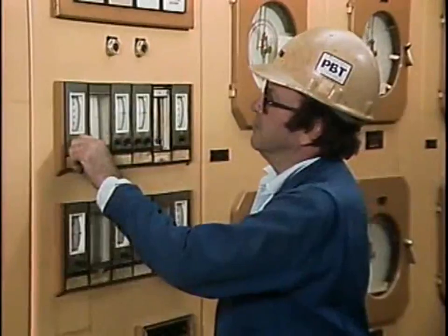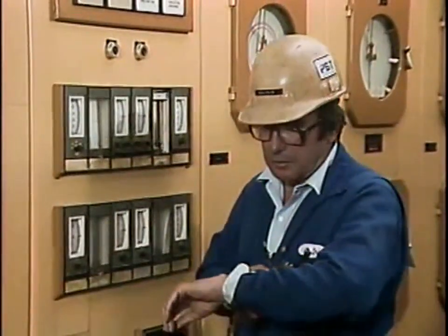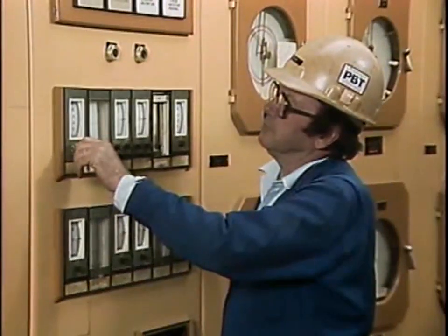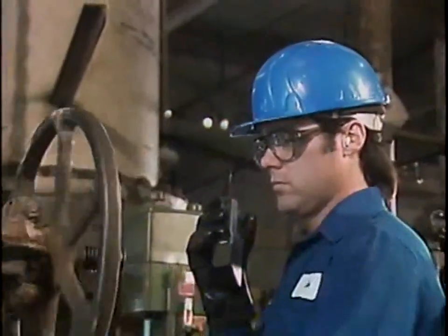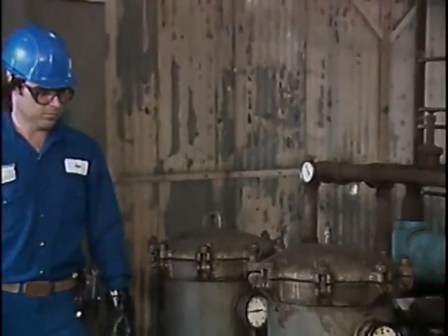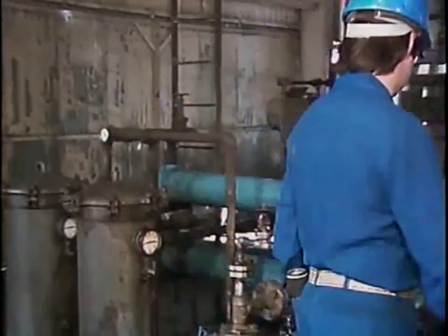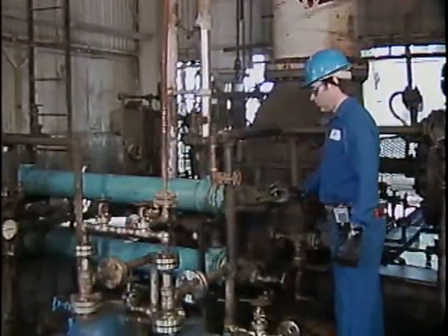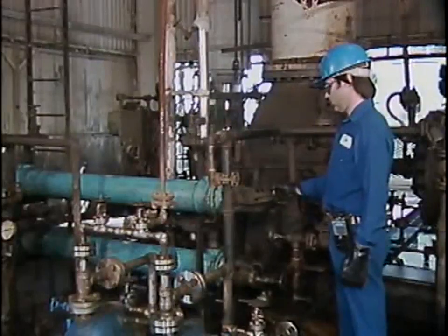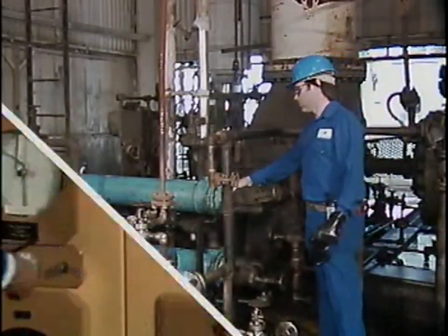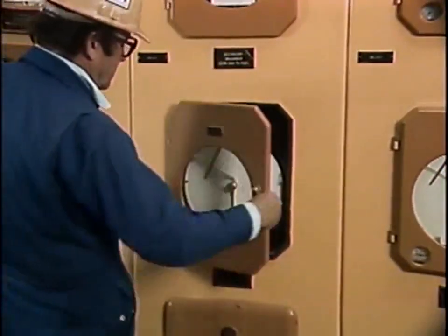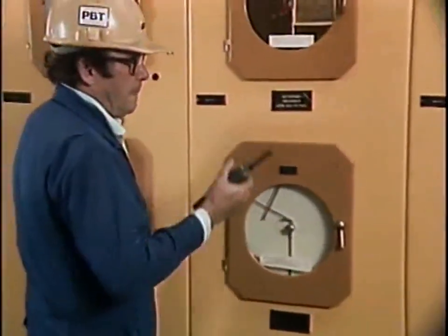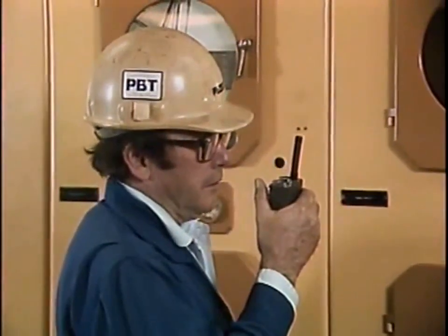Once the compressor has been purged, it is started and allowed to warm up. The steam turbine is started at a low speed to allow the compressor to warm up. The steam turbine is started by opening the steam supply valve. As the compressor is warming up, it's important to make sure that the proper flow of cooling water is maintained to the lube oil cooler. The compressor could be damaged if the lube oil temperature is allowed to get too high. The internal parts of the compressor and its driver must warm up gradually to prevent stress and potential damage. For this reason, it's important to keep a close watch on compressors while they're warming up.